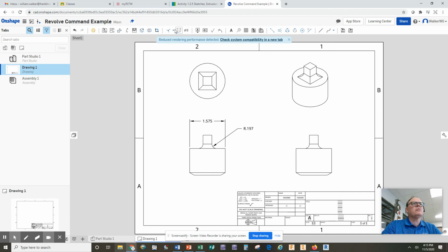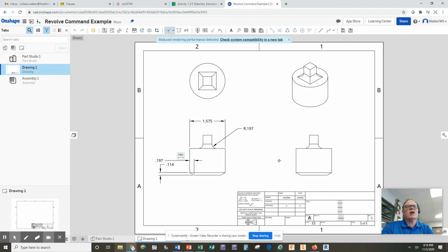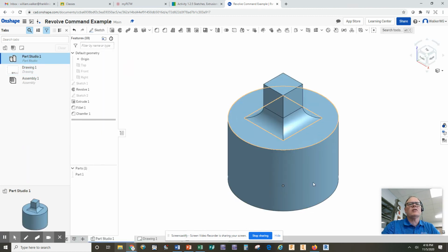Anyway, you guys play with the chamfer tool. I'll work with it here and see why it's not behaving right. It's done that on other drawings correctly. But you're supposed to be able to click on these two, and when you pull it back, it's supposed to give you a dimension that looks like this, where it shows a 5 and a 30, and somehow it's not doing that. But anyway, make sure you guys end up with the drawing. Now, I haven't put all the dimensions, so you need to add more dimensions to this. And you want to create this part using Revolve, Fillet, and Chamfer, and you'll be on your way to being a better CAD operator.